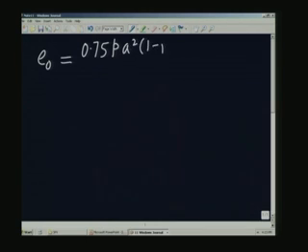So, we already gave an expression earlier. The output of the gauge in terms of millivolts per volt was given as 0.75. We just recapitulate P A squared (1 minus nu squared) divided by E T squared into 10 to the power of minus 3.